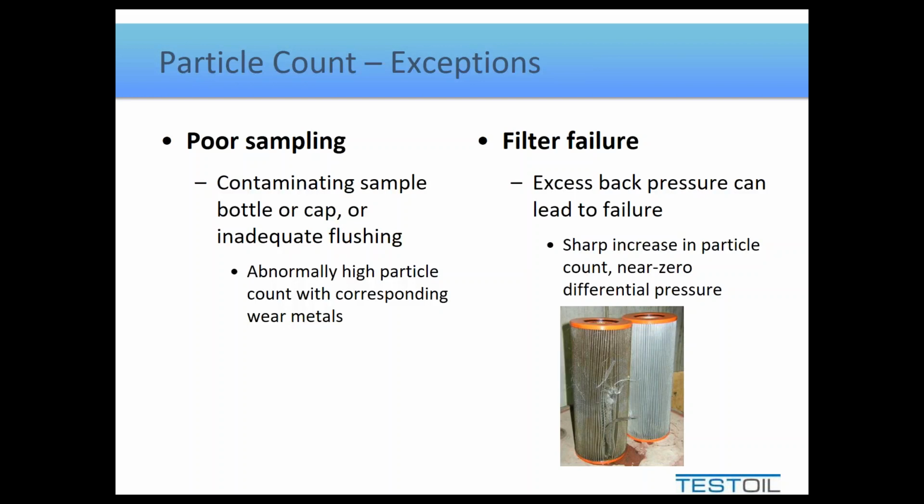But there's one other way that is relatively common to see fluctuations within particle count data that I'd like to speak to, and that is namely the sawtooth pattern that some people see over time, meaning that the results begin low, they start getting higher, higher, higher, and then there's a drop-off, and then they're low again. And they go low, higher, higher, higher, and then there's a drop-off, and they repeat this pattern over time. This type of pattern is typically seen in systems where there are filter changes throughout the life of the oil.